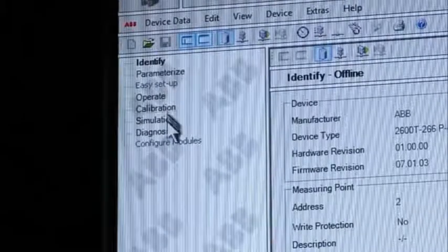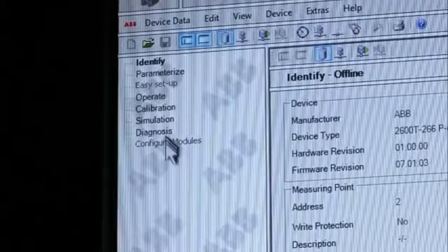If we decide that there is a fault with a particular instrument through the intelligent data, then again we can simply right click, and assuming a SAP or a Maximo computerized maintenance system is connected, we can generate electronic work orders directly from the right click. Not only that, we're also able to get access to active work orders, spare parts and work order history directly from the HMI.